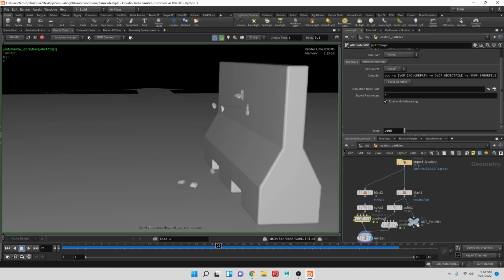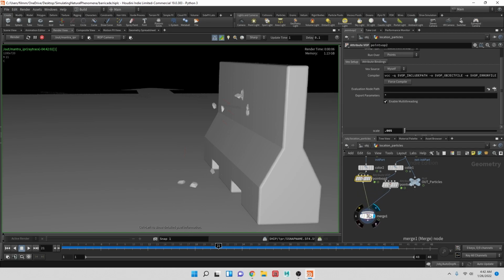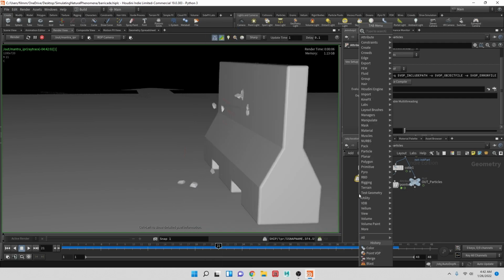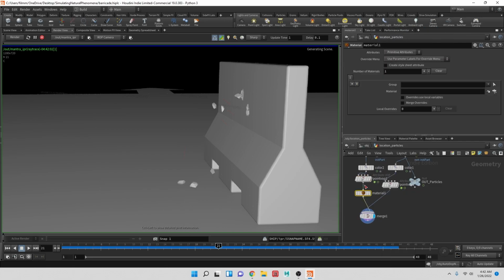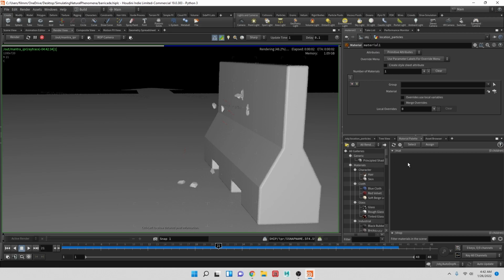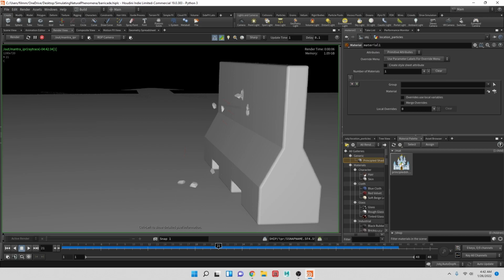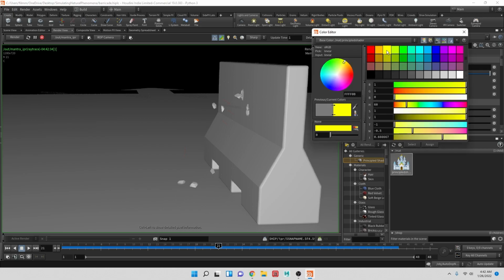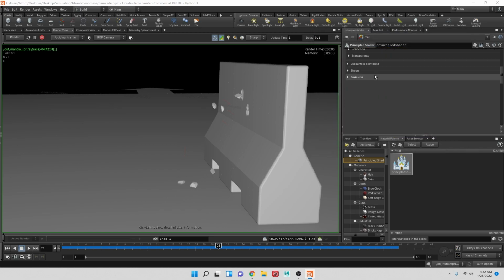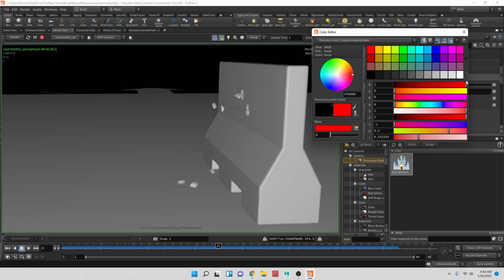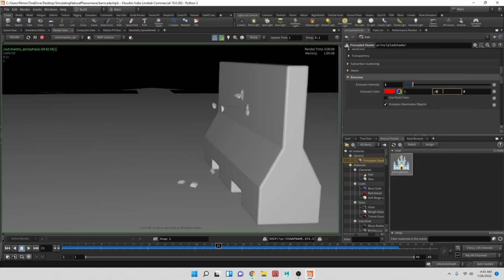So what I want to do also is add a material. So this is the spark side. Let's do a material here. And let's create that material. It's going to be based off of principled shader. There we go. And let's try something like that. And then an emission. Let's do red. Let's put this at 0.01, 0.01. It's still going to look red, but that will give us an opportunity to adjust things. And the name, let's call it Spark.